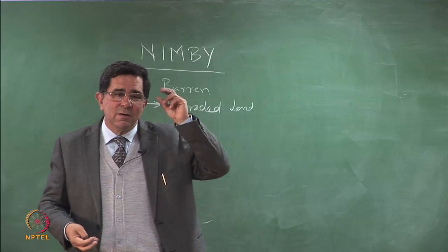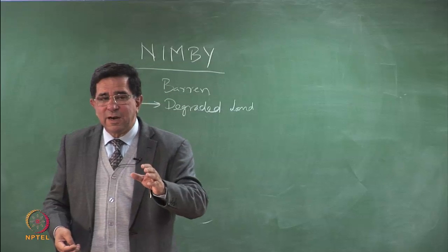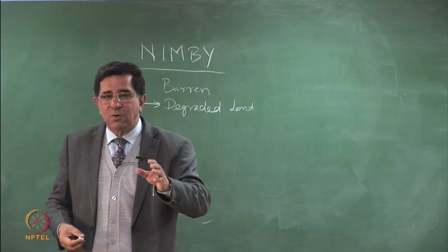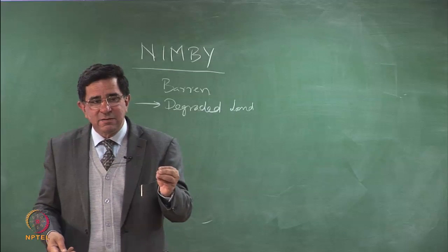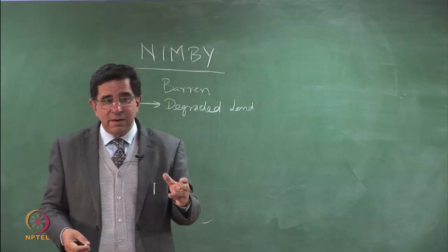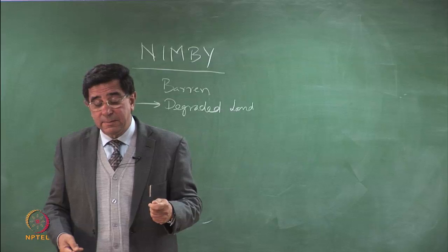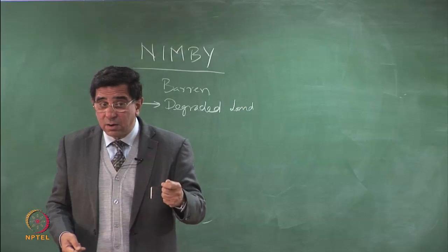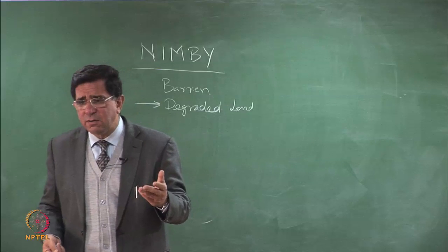The immediate bell which rings is that the site where the groundwater table is 2 meters below the ground should be avoided, because if there is any leakage, groundwater will become immediately contaminated, and if it is drinking water, then there will already be hand pumps in that area. So people will be using it all the time.